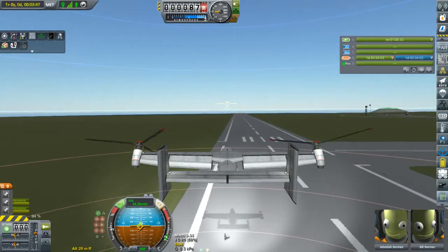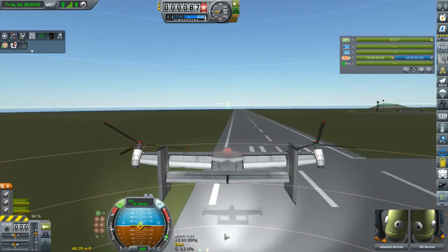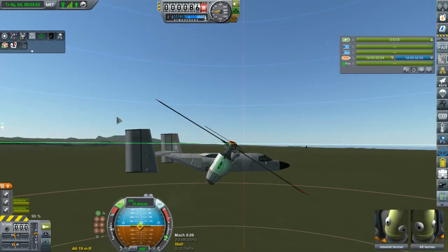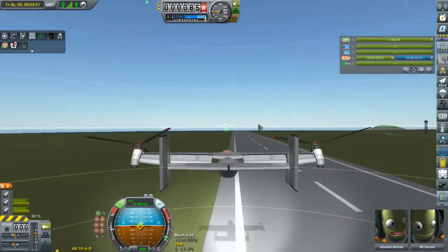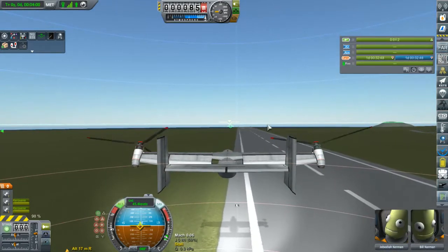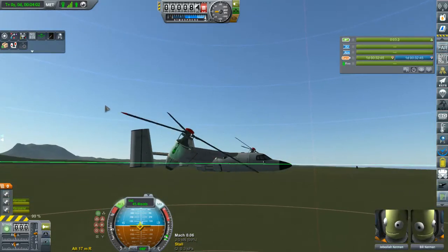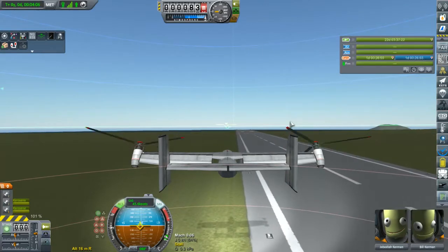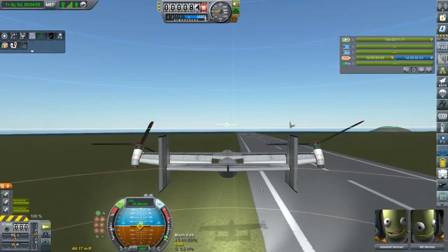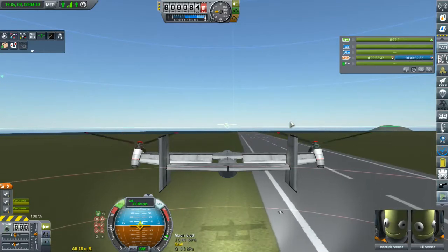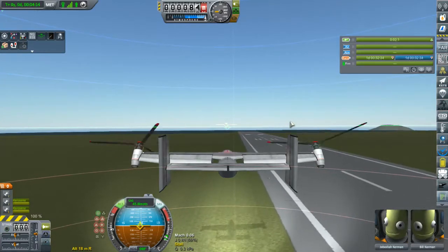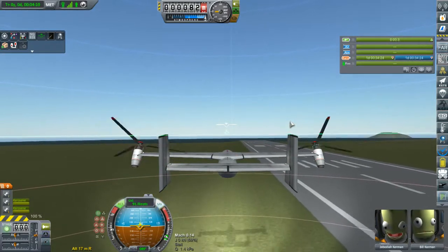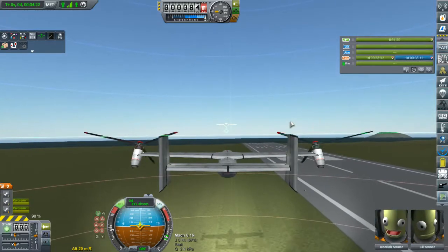And now we're flying at approximately 44-45 knots. We're almost to a 45-degree angle on the nacelles. But because of all the drag produced by these absolutely huge skirt flaps, as I like to think of them, or cape flaps, we are just not accelerating at all. But when I raise them, see a great increase in speed.